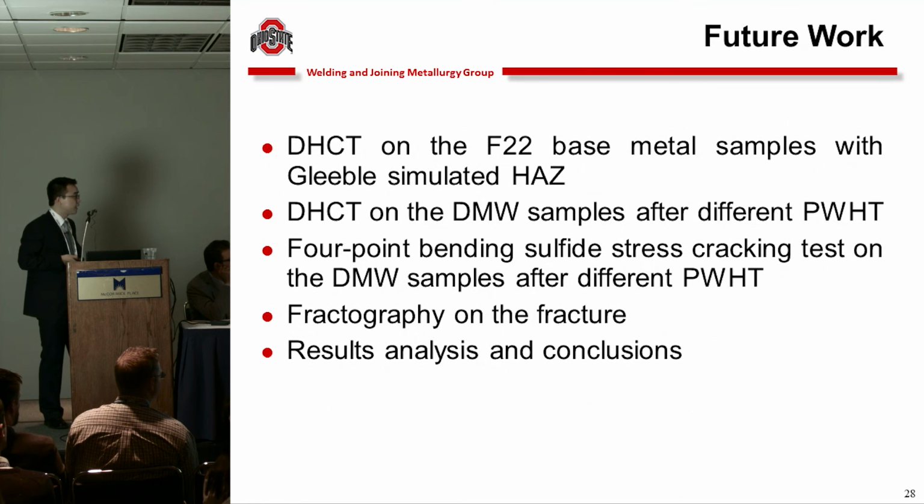Future work includes the delayed hydrogen cracking test on the F22 base metal samples with Gleeble simulated heat affected zone, delayed hydrogen cracking tests on the dissimilar metal weld samples after different post-weld heat treatment, and four-point bending surface stress cracking tests on the dissimilar metal weld samples after different post-weld heat treatment. And fractography work on the failed samples or fracture surfaces. All the results will be analyzed and the conclusions will be made for the final dissertation.